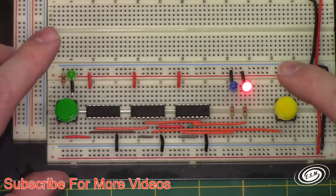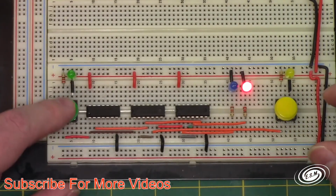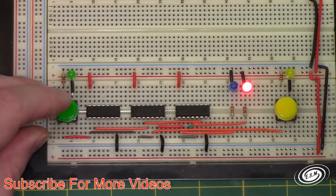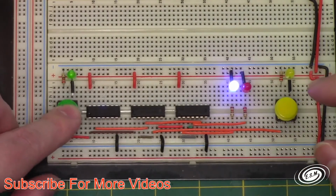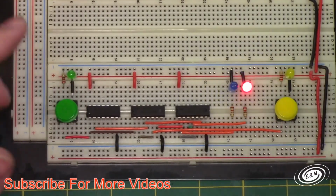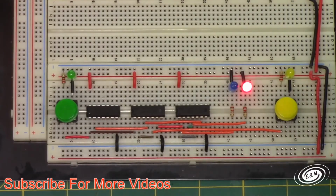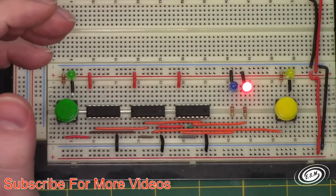So in order to put a high in, and now I can press enable all I want without pressing anything else. I can press data all I want, and it stays in that last state. So if I want a 1, then I can do that. But if I reset it by inputting a 0 in the data, it resets it. So this will store a bit of data in this D-type latch.